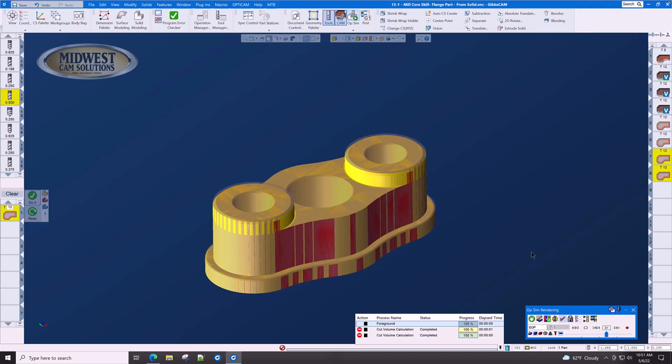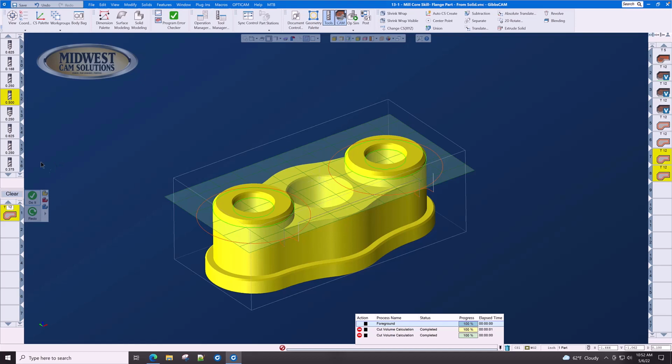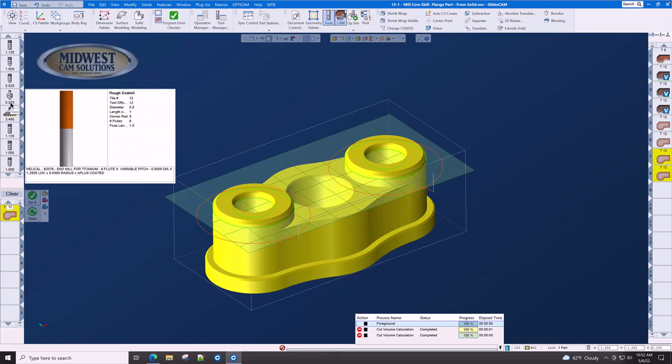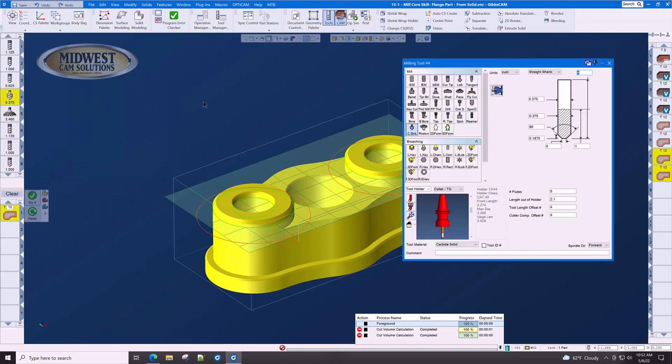as we get through the roughing and finishing of this part. Now that we're into the finishing, we're ready to cut the chamfers here, here, here, here, here, and here. And we're going to use our countersink and the same contour process. Let's look at our countersink. We have a 3/8 countersink here.